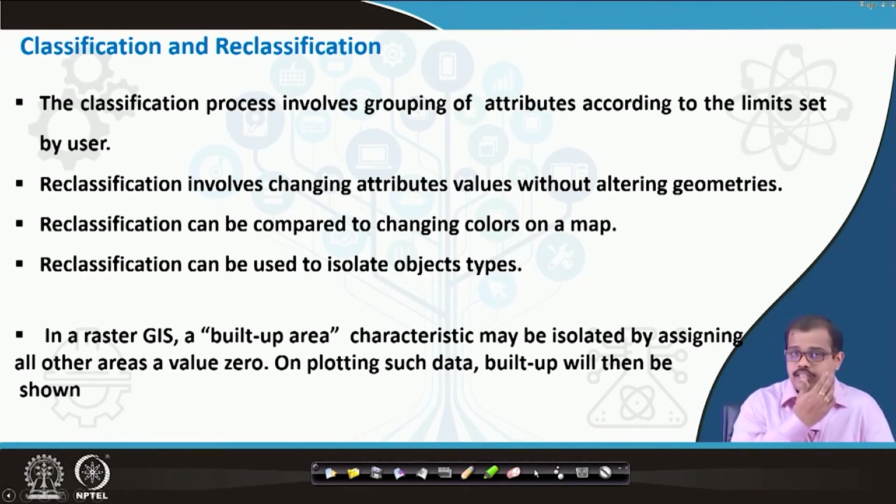Another way of classification in raster data is automating it through supervised or unsupervised classification. In supervised classification, a user gives the input in terms of signatures, which trains the classifier using statistical measures such as mean, standard deviation, variance, covariance, etc. Using all these values, the classification happens. A huge number of classification systems have been developed over time, such as land cover and land use.